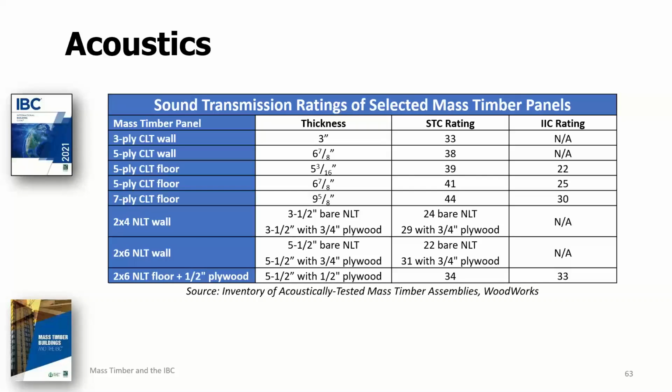This is one of the main acoustical design distinctions between lightwood frame floor ceiling assemblies and mass timber floor ceiling assemblies. In light frame construction, acoustical components are typically included both above and within and even below the assembly. For example, you have underlayment and or concrete topping above the framing.